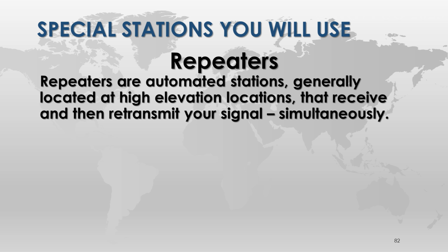What is the control operator operating then, just for everyone to use? It is an automated station, so you're making sure it's working all the time. Her responsibility, and mine, because I manage it for her, is to make sure that it's functioning properly. It's not just locked on and transmitting. It actually has a timeout timer on it, so I think it's 3 minutes. If it transmits for 3 minutes, it'll shut down. And then it'll turn back on.